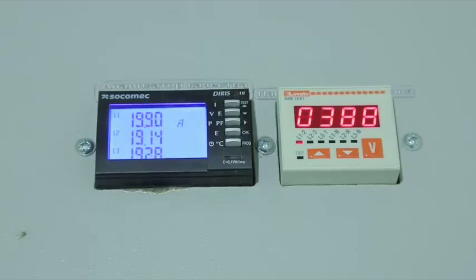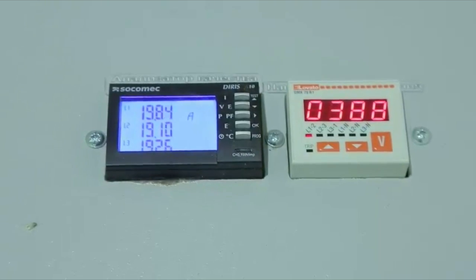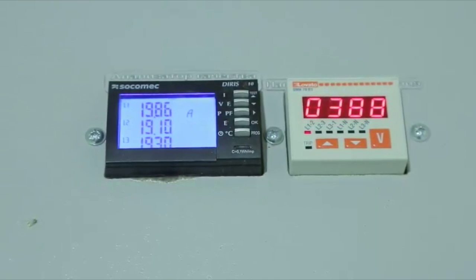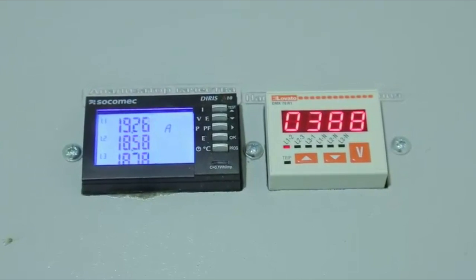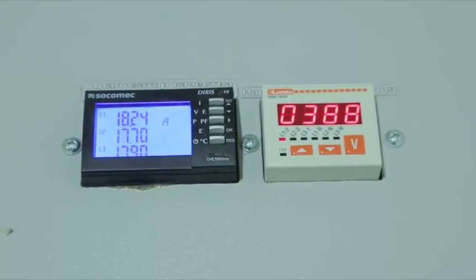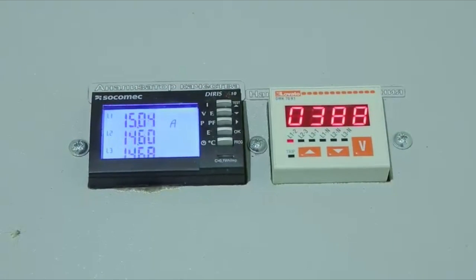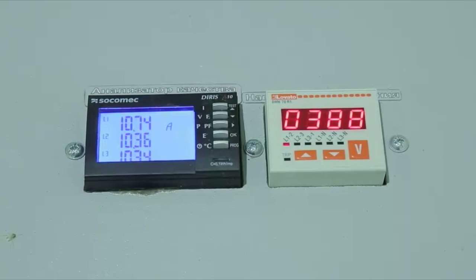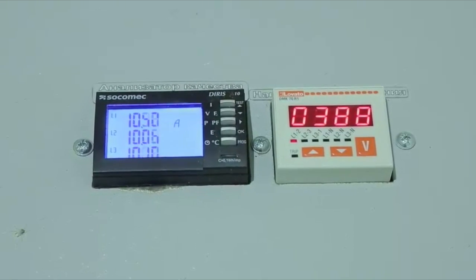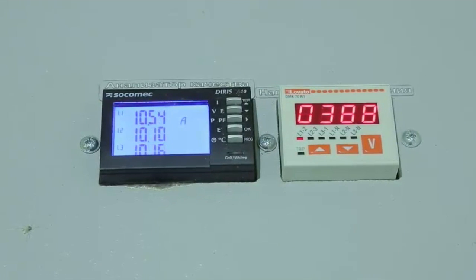We will monitor the motor's consumed power by current and voltage displayed on 3-phase multimeters. We monitor currents and voltage of the set mode. The device analyzes operation of the asynchronous motor and within a time interval of 30-35 seconds reduces power of the motor without changing the number of shaft revolutions. We observe reduction of operating current of the asynchronous 18.5 kW motor. Total saving of consumed energy in idle mode is 50%.